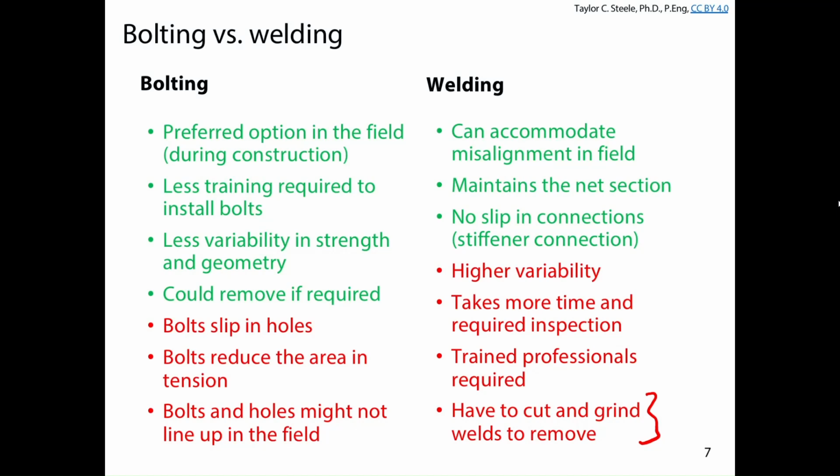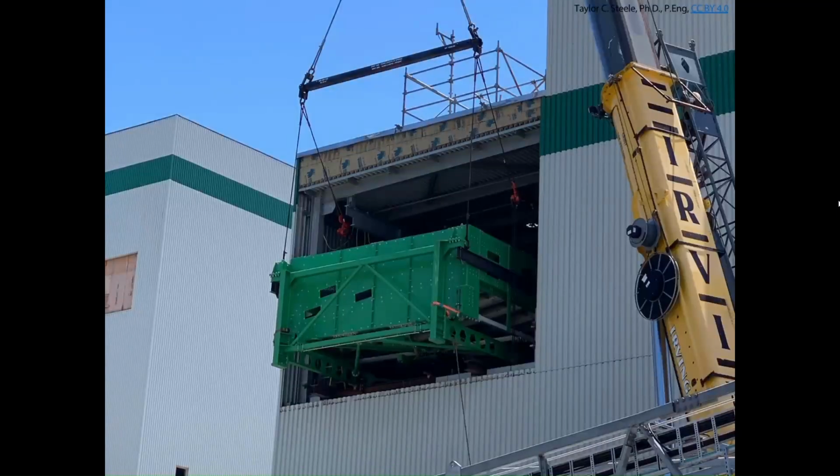For example, I was working on a project once at a pulp and paper mill, where they were upgrading to sort the size of wood chips to generate the pulp that they produce at the pulp mill. And the only way to avoid spending several hundred thousands of dollars was to remove the bracing that was here. The only way that they could get this machine in was to remove this metal panel siding early so that they could crane those chip screens into place. You have to have a really sharp pencil and know what you're doing to approve the removal of bracing in a structure, but you can generally make it work.